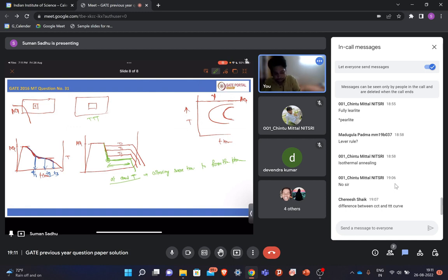But here the temperature is continuously decreasing, right? You are not quenching, it is continuously decreasing by furnace cooling or like this. So in this case you are not allowing time at this temperature, you are just directly quenching it. So the fraction formed up to this point is not because of this temperature only, it is because of the accumulation of this continuous transformation over this temperature range, and then you are cooling it, right?